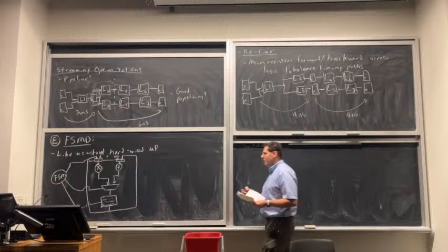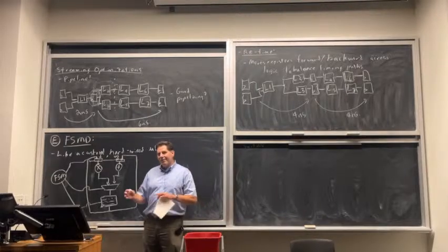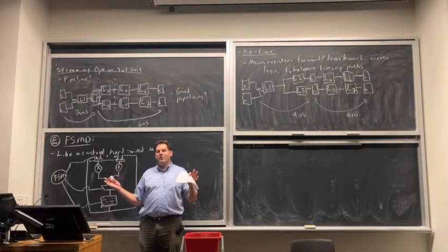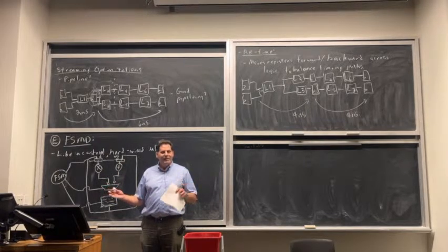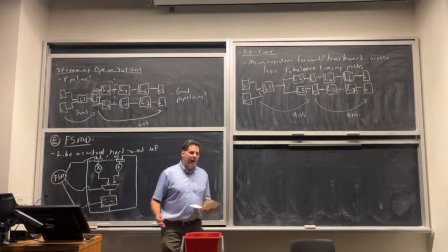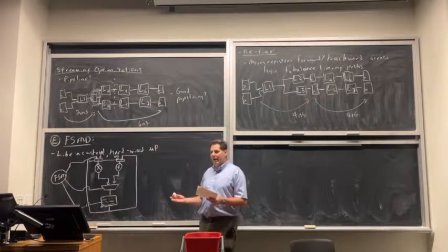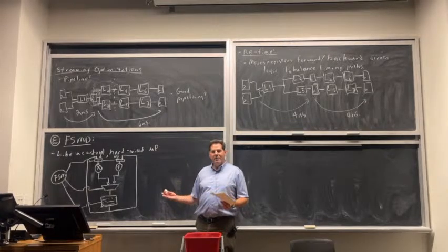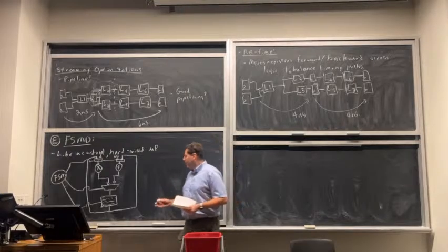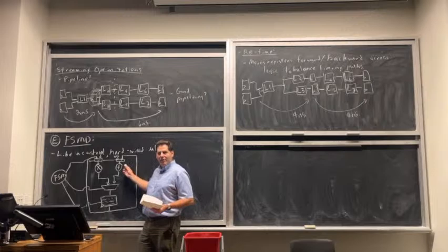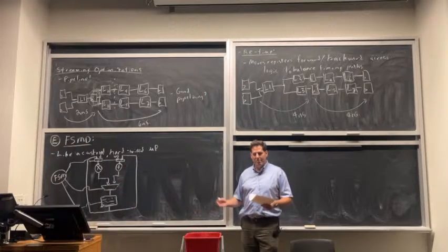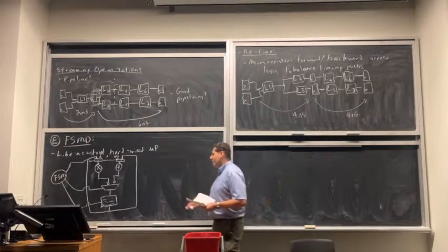So one of the things you're asked to do in Lab 1 is, well, often in a chip you have multiple choices. You can put as much stuff in as you want until the chip is full. So if this is smaller, you should be able to fit more of them in. On the other hand, it's probably not going to get as much work done per unit time. What's going to get you more throughput? Should you just have a higher number of replications of this? Or is the streaming hardware, despite its larger size, going to more than make up for it by being so efficient in throughput? So those are some of the calculations you're going to do.